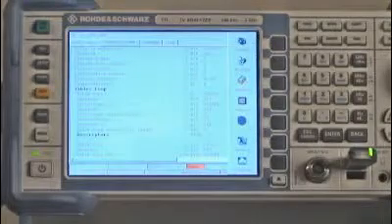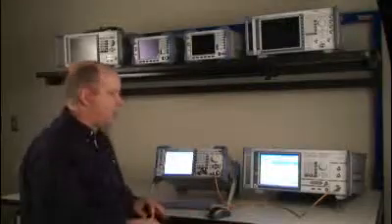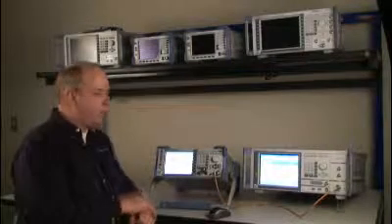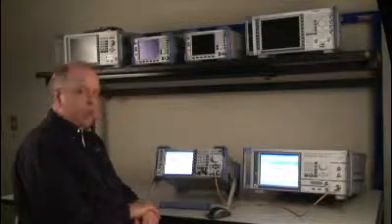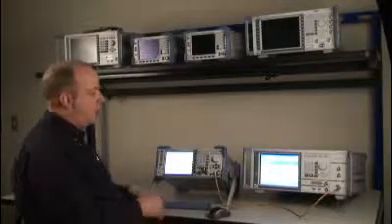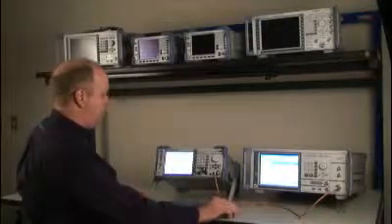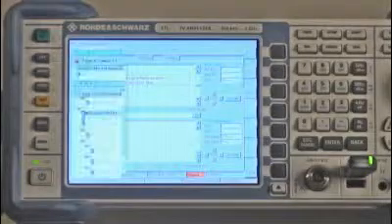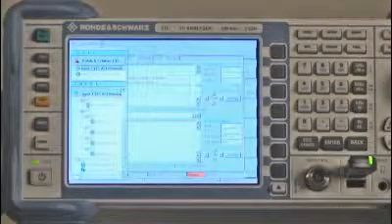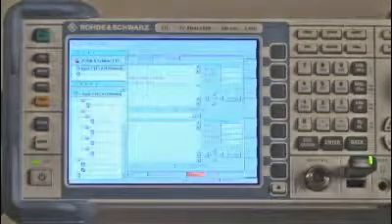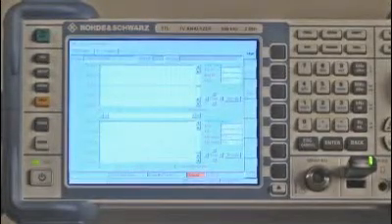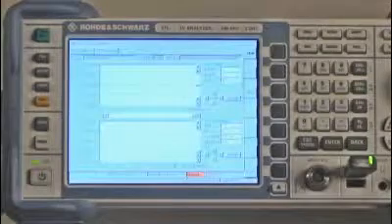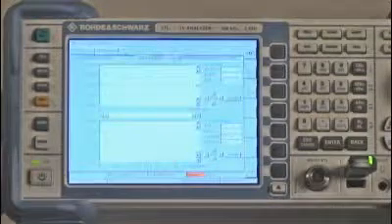The next one is advanced. The advanced one is actually an option within the MPEG measurements. And what we can do in this area is actually show the PCR, or program clock reference. So I'm going to come down and select on the left-hand side my video, which is where my PID for the PCR is usually associated, and then hit start.